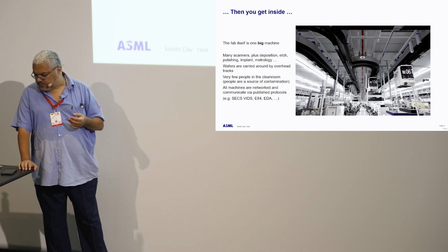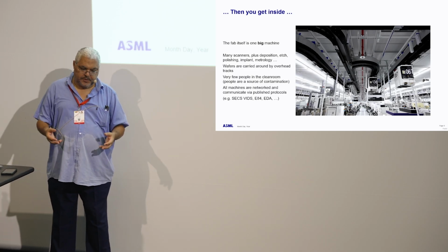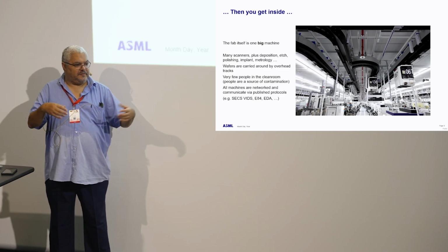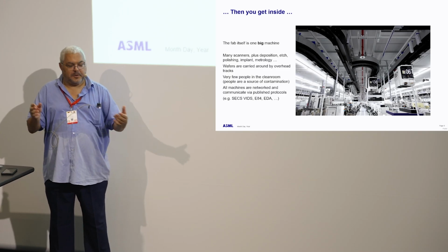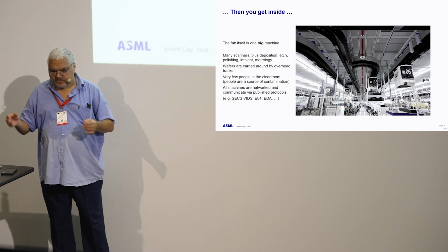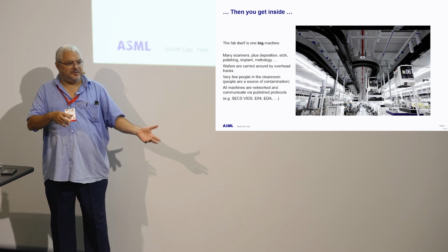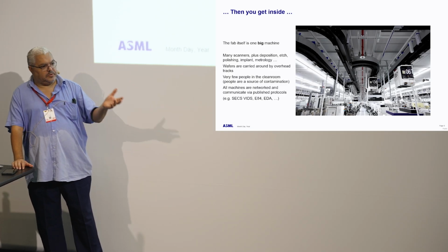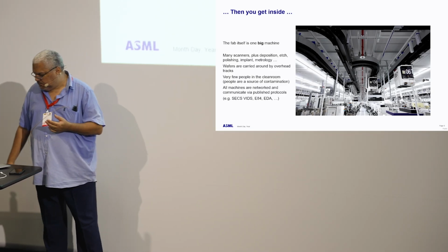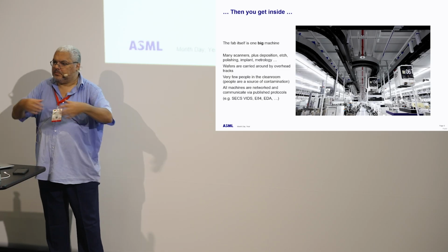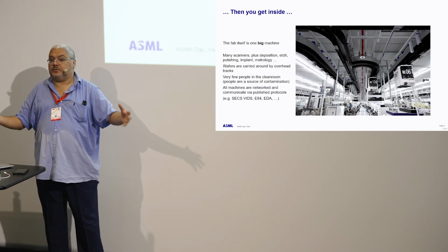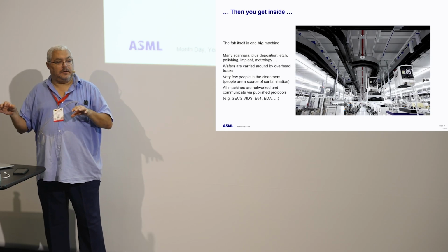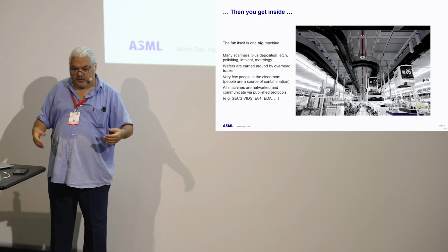There are others, like one called E84, which is about the handoff of materials. So it contains ready flags: okay, I'm ready to pick up a FOUP. I've unlocked the doors. I've picked it up. Ready to receive a new one, and so on. EDA is a mechanism for getting reports, and so on. And so, as you can imagine, this complicated machine has to run 24/7. In order to make people money, this thing has to be printing wafers.